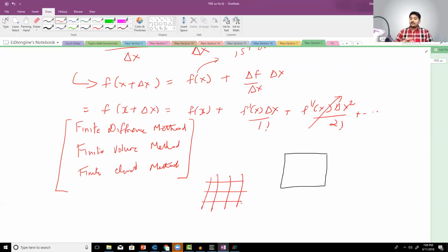And that is why finite element method is typically used for structural simulations, whereas finite volume method is typically used for computational fluid dynamics simulations. Finite difference method can be used for all of it for simplified cases. So that is why when you try to learn CFD, people typically teach finite difference method because it helps you learn all the fundamental concepts in CFD.